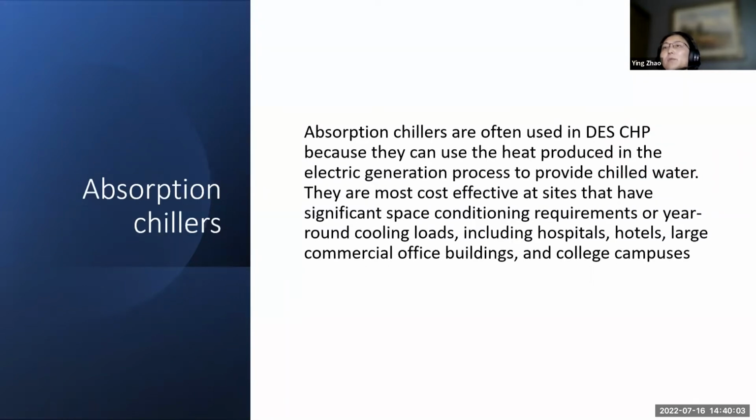And about absorption chillers, we talk about that because it doesn't use electricity to power the compressor. It can use heat produced in the electric generation process to provide chilled water.